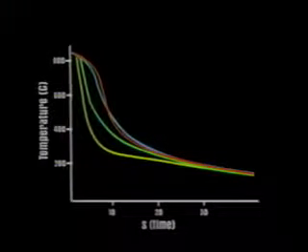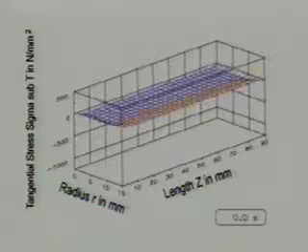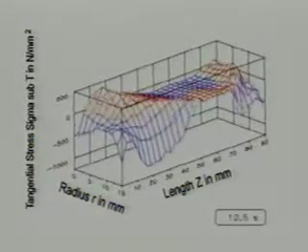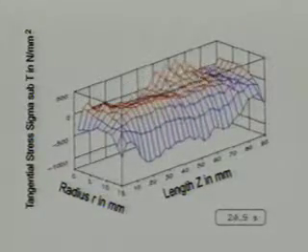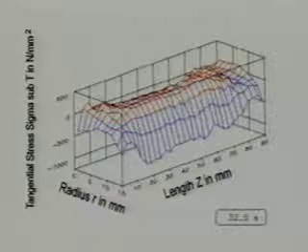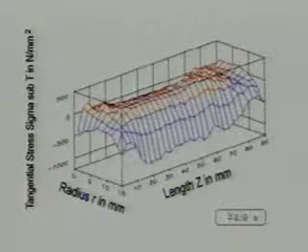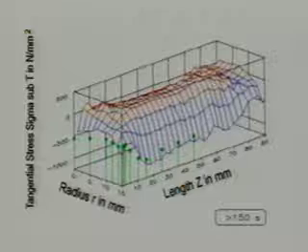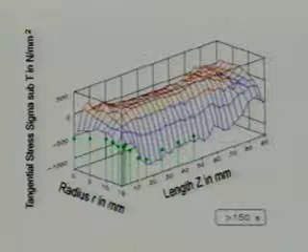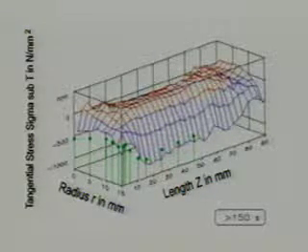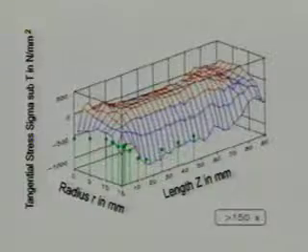In this experiment, a cylindrical probe with a center thermocouple was immersed into an oil quenchant, and a cooling time temperature curve was obtained similar to the process shown here. The thermal gradients that are formed during this quenching process are shown in real time here. This improvement in cooling uniformity will reduce thermal gradients and, if proper quenching conditions are used, also reduce the potential for excessive distortion and cracking.